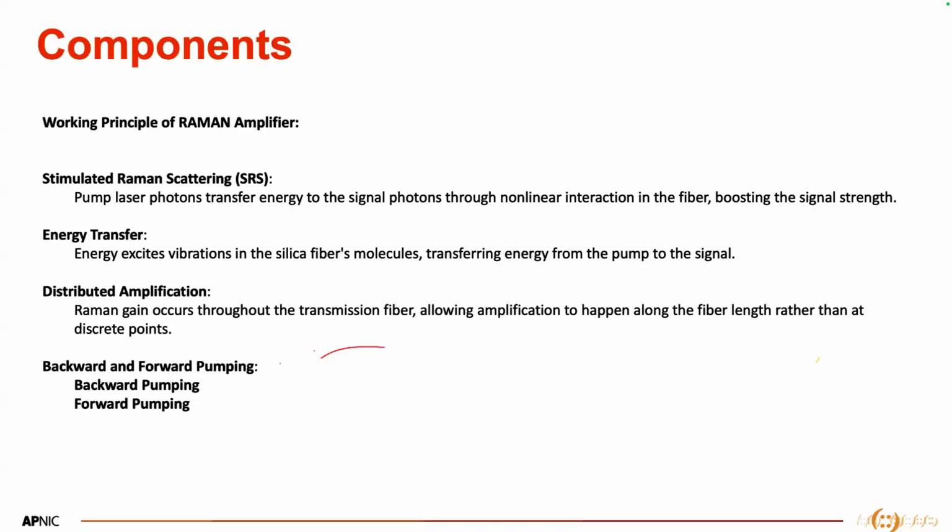Raman amplifier is very expensive, and it reduces the noise, and it improves the signal to noise ratio as well. So for using Raman amplifiers, you need to have a special kind of patch cords as well, because of the high laser pump at the source. If you do not use special patch cords, your patch cords are going to get burned every now and then. So that is one thing you need to take care of.